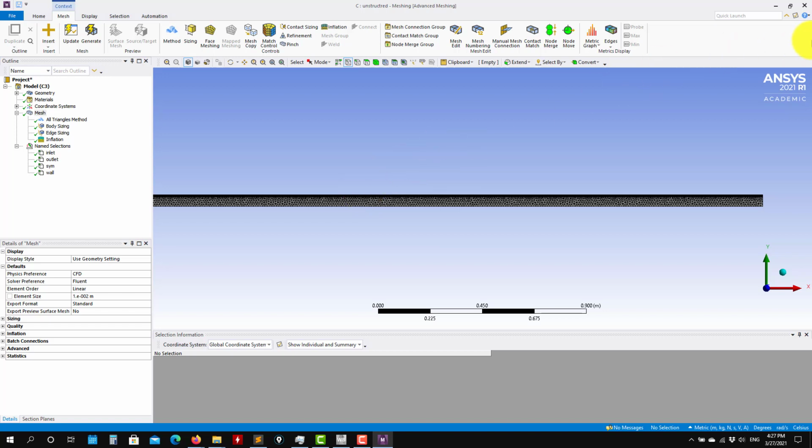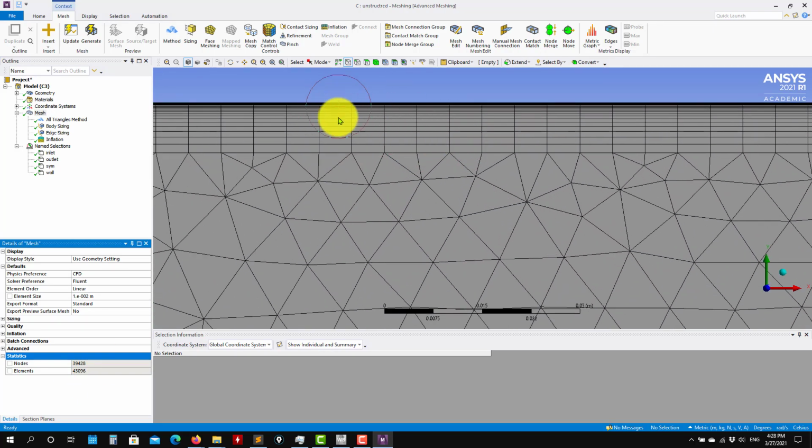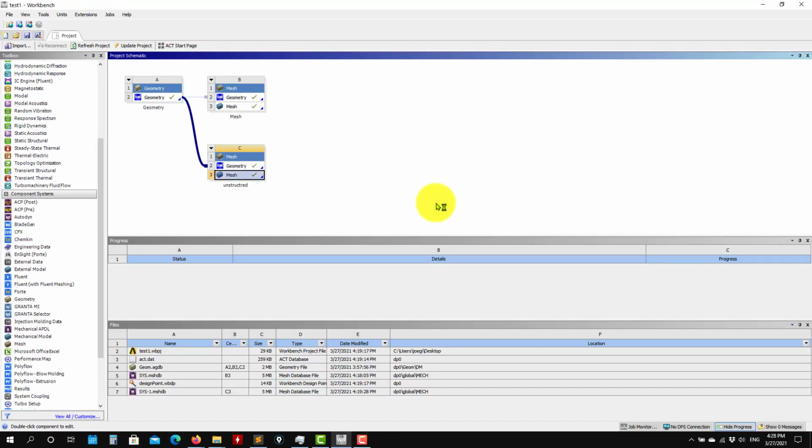So now that we're done here, let me see the mesh count. So see that even though probably we have better control in the boundary layer, we have fewer cells than the other. Usually also structure meshes have the tendency to use more cells. But in any case, everything can be controlled. So see that now you have the two meshes.